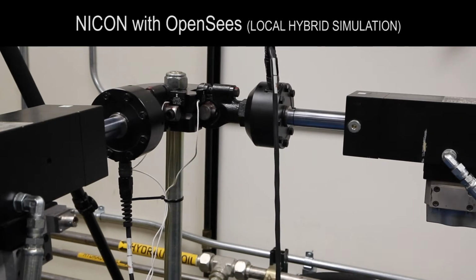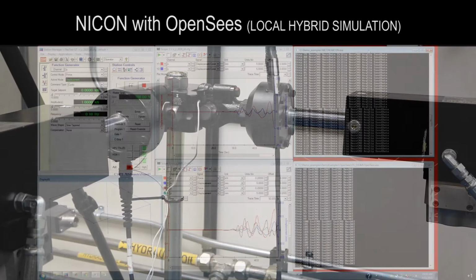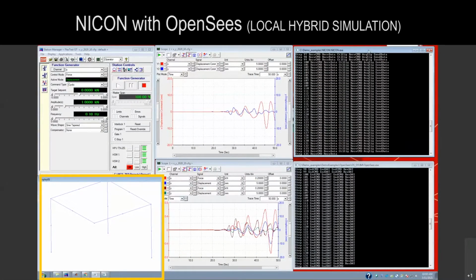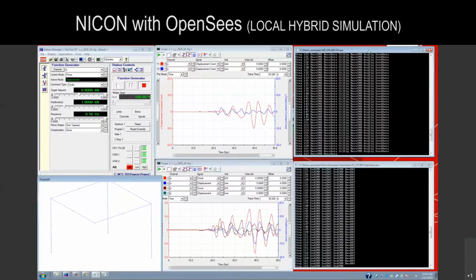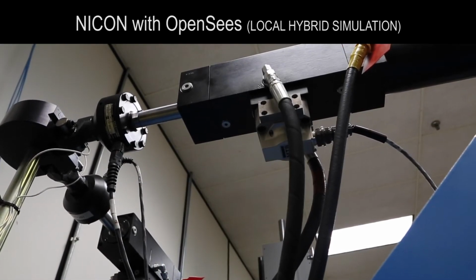There is an animation showing on the bottom left corner of my screen, showing how the numerical substructure is moving. Again, the boundary condition is enforced at that interface node. So basically, that numerical substructure is synchronized with the physical test substructure to perform the entire hybrid simulation.